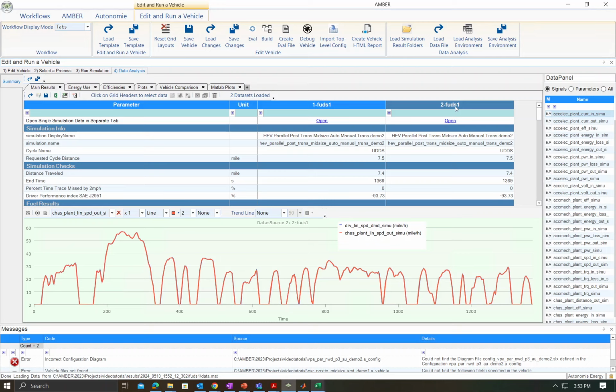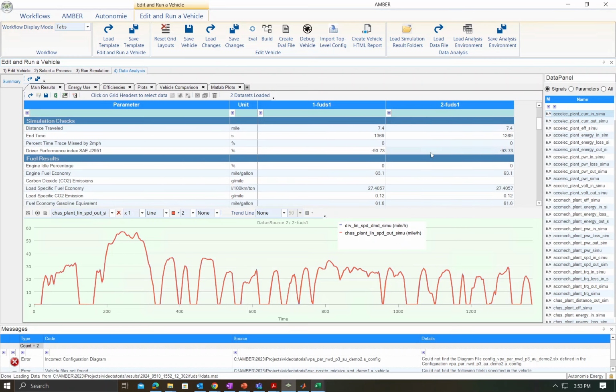But the gear ratio that we have added is 1. So it is basically not having impact on the powertrain, because the motor has to operate at the same RPM and same torque level. So the fuel economy is not going to change because the ratio is 1.